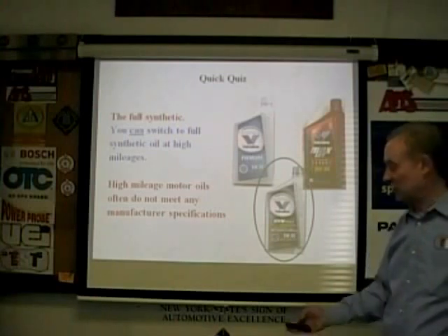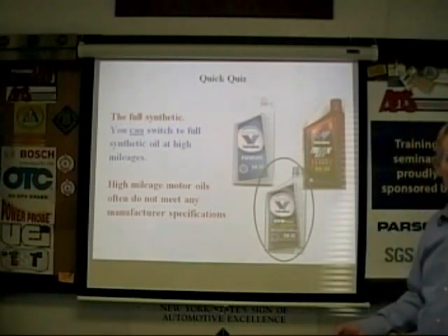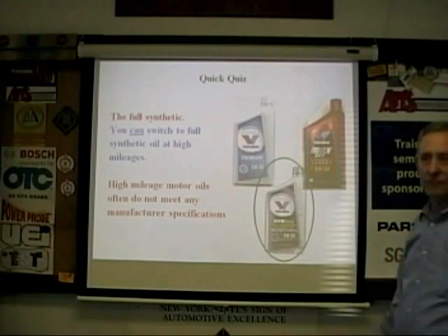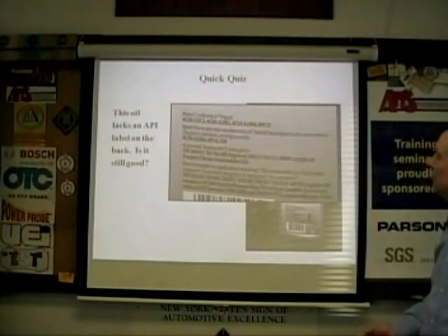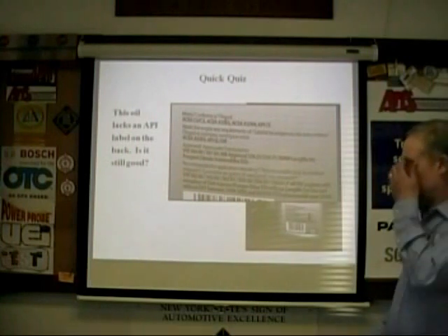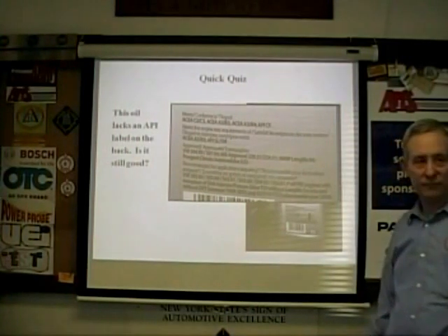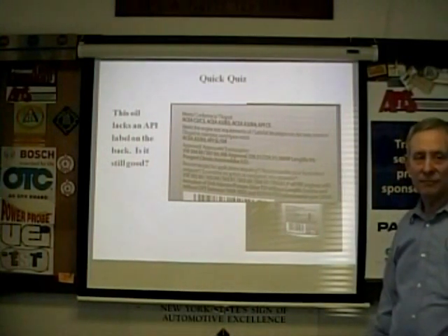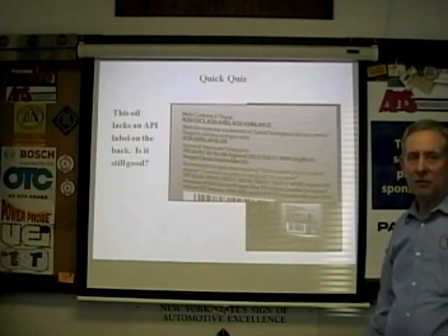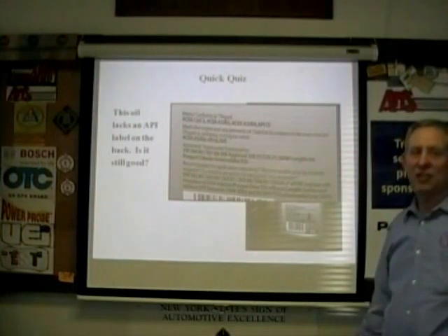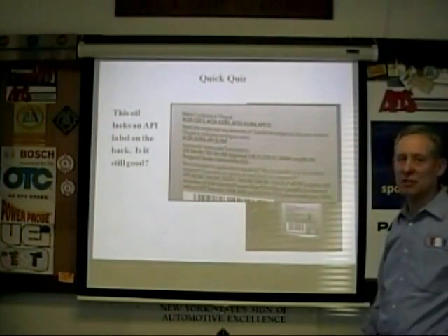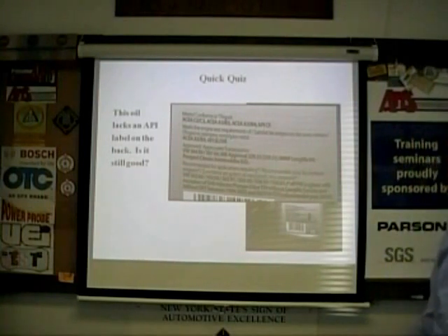You'd probably have to flush it out with a... I did that on my Jeep. I always changed the oil every 3,000 miles, and I used regular oil in the beginning, switched over probably the last 10,000, 20,000 miles to synthetic, and no problem. But the older cars, when customers wanted to switch, they had seal problems. They had seal issues. I don't think that's true anymore, but only because the chemistry of things like seals has gotten more stable.